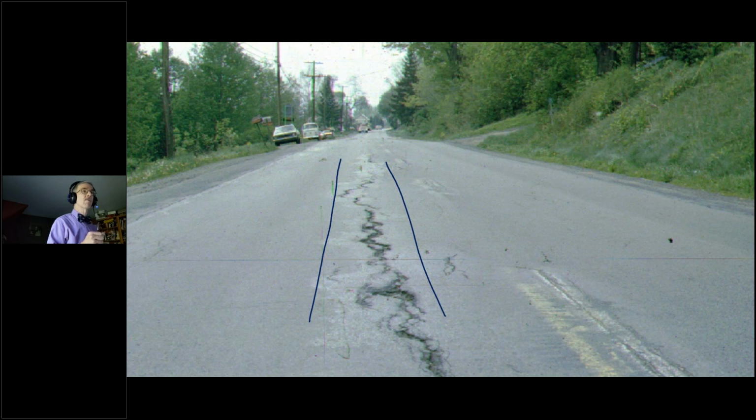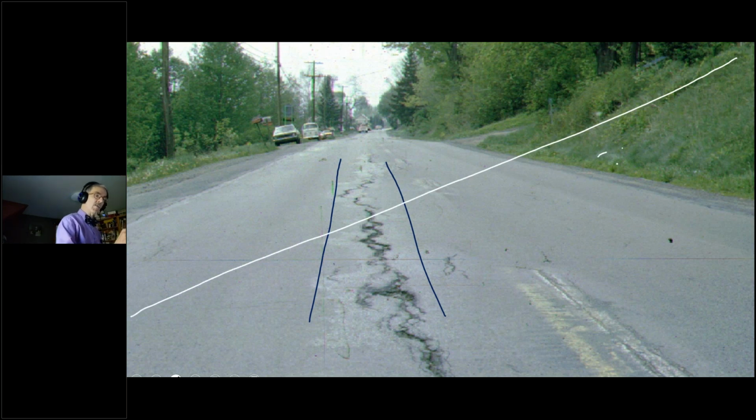We'll make it work. This is a side hill situation, and the road actually goes from a cut over here to a fill over here. And what we're seeing, that cracking actually is fairly close to the interface between the cut and the fill section. And the real problem is a combination of that and the fact that there's water coming in from the side. So the first thing I would want to make sure is to cut off any kind of water coming from the side and keep the water out of it.